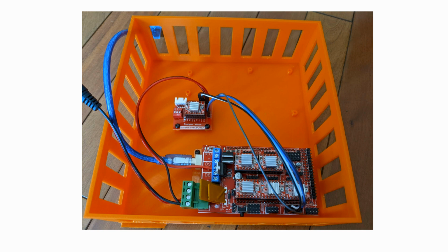In addition to making the wiring much neater, another benefit of using RAMPS 1.4 is that we can use open source firmware to control the motors. Here I use Marlin, which is an open source firmware for 3D printers. We store it to Arduino. Then we can send commands as G-code to Arduino. I will talk about G-codes later when introducing the software.